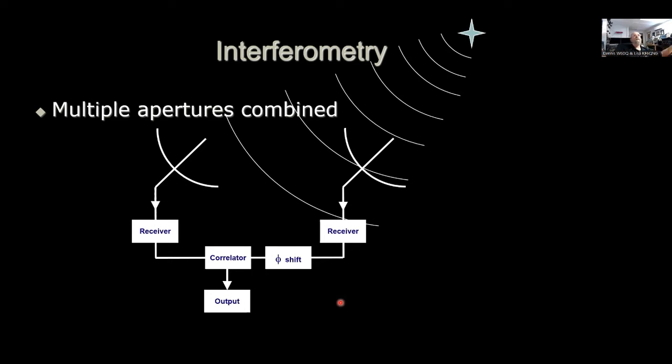So the antennas are maybe a few thousand feet apart, and you've got a couple of thousand feet of coax feeding them. Your phase shift is done by changing the length of the coax, by switching in different lengths of coax. The next step from that was to go optical, and they use fiber optics and switch in different lengths of fiber optic to change that phase shift.